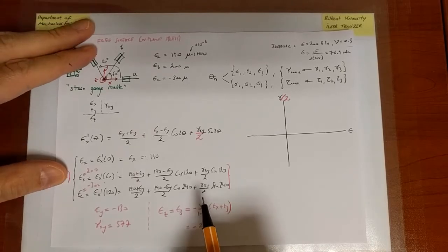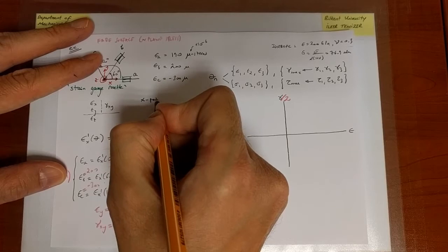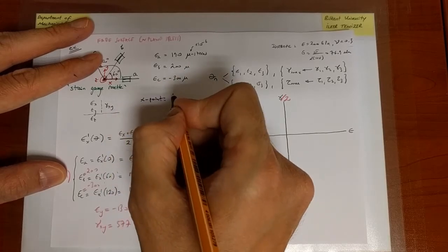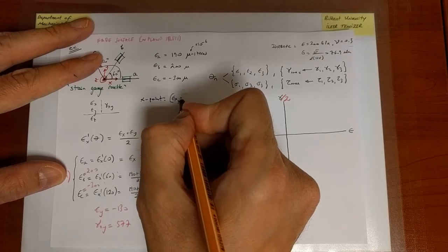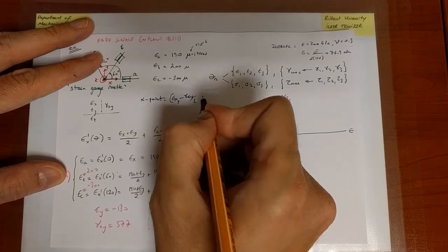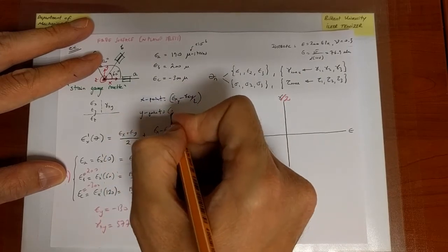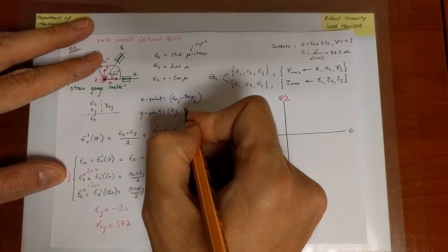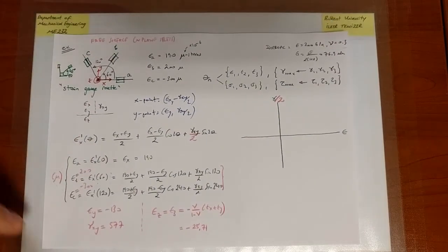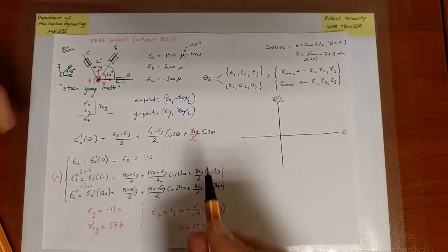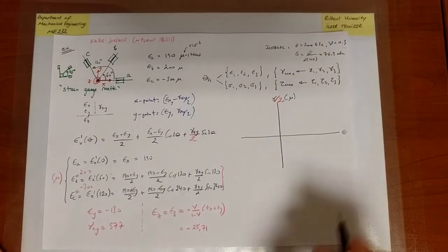And so now I'm going to go ahead and put in the correct values of the points. So I will obviously have an x point for the strain, exactly as before. So it's going to be epsilon x, minus gamma xy half. And the y point is going to be epsilon y, plus gamma xy, but don't forget the half. Okay? So again I assume that everything here is in terms of microstrains.